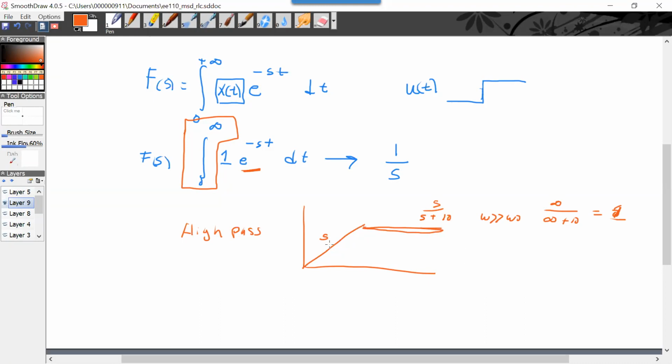So in this region where we're rising up is s. And if we recall, high pass filters detect the edges. So if I put in a step, I get this exponential decay where, hey, there was an edge there, and then it decays. So that is like taking a derivative. Now, what if this was like 10 gig? That would mean most of the frequency range, it's just acting like you're taking the derivative, because if omega is a lot less than omega naught, you get s, or no, sorry. Yeah, you get this. Okay.